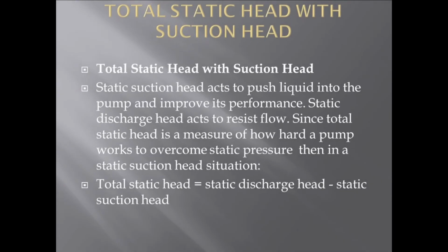Total static head with suction head. Static suction head acts to push liquid into the pump and improve its performance. Static discharge head acts to resist flow. Since total static head is a measure of how hard a pump works to overcome static pressure, then in a static suction head situation, total static head equals static discharge head minus static suction head.